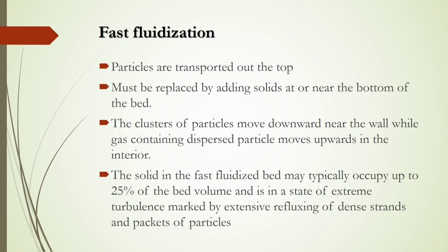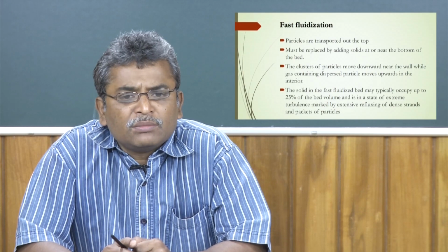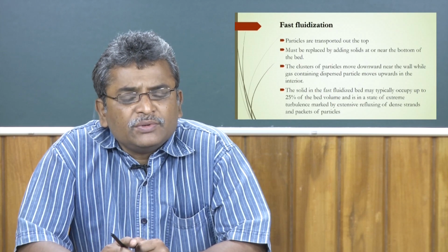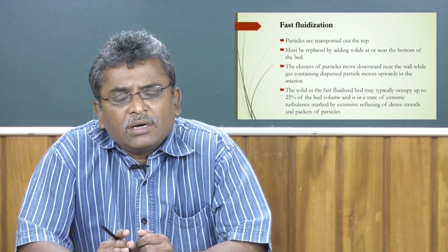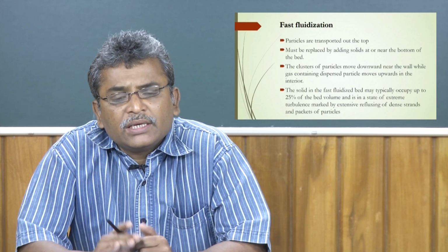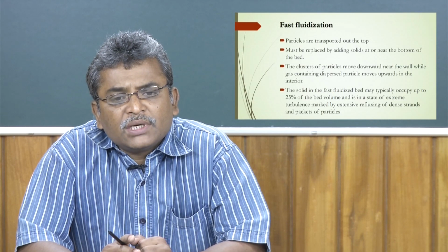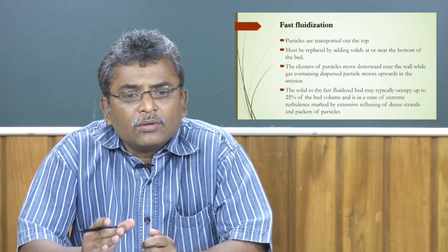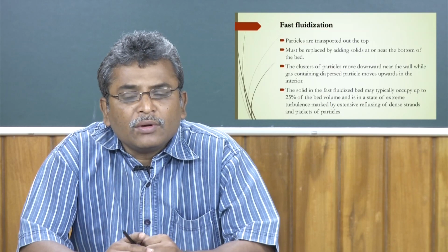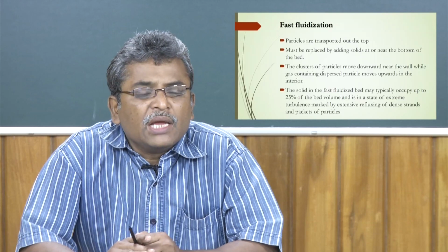Of course, you have to add the solids near the bottom of the bed, because at this operating condition if you supply from a certain height of the bed, it will go immediately to the top and will not have that much retention time inside the bed.